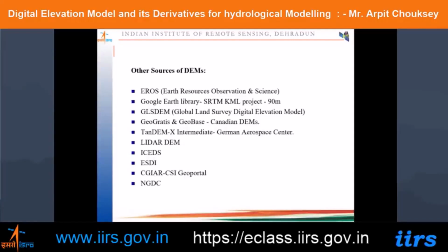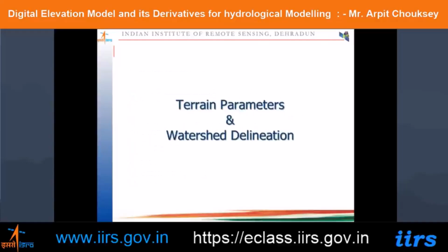And let me tell you first, before discussing the terrain parameters, the errors in DEMs. There are several errors in DEMs that you can download freely from different sources. The most common varieties of errors are sinks and spires. Sinks occur where a very low elevation relative to surrounding cells is entered, and spires occur when a very high elevation relative to surrounding cells is entered. Both appear as tightly packed contours. So it is better to remove these types of errors before proceeding ahead.